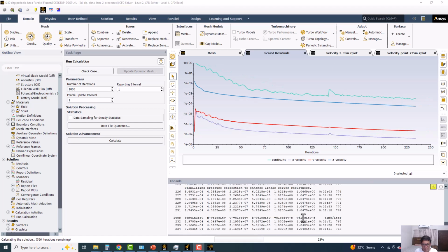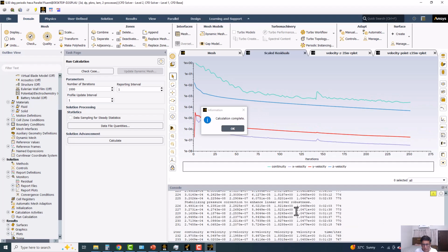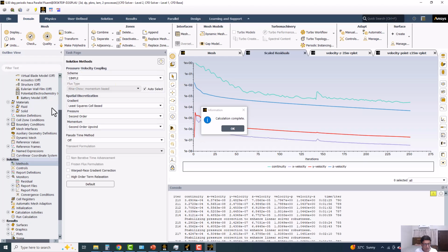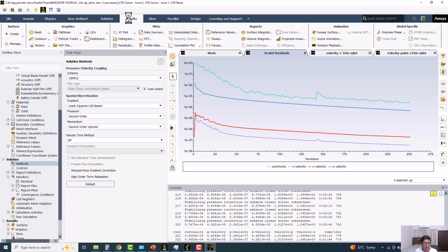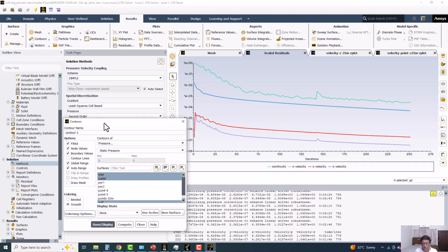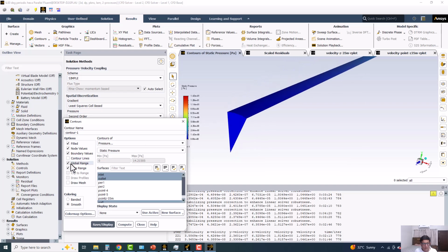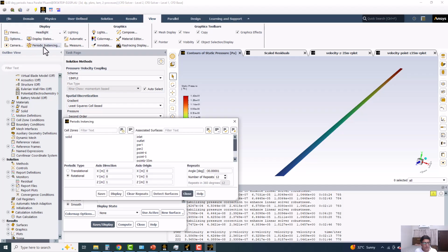We have the stability issue, but now it is gone. Okay. What was the warning there? Okay, we have the SIMPLE. Yes, we have the SIMPLE, but still it was giving us some problems here. So let's check the results. Then I will continue actually for 1,000 iterations. With the SIMPLE method, you have to run for more iterations. Okay, and product is instancing, and it's product 1 and 2.